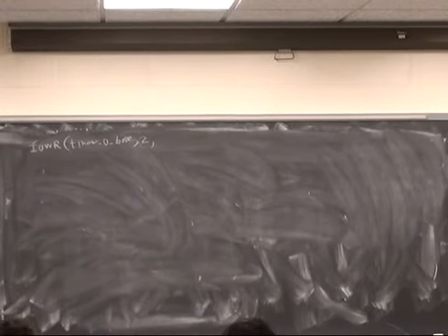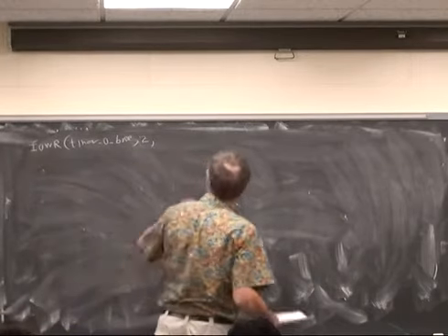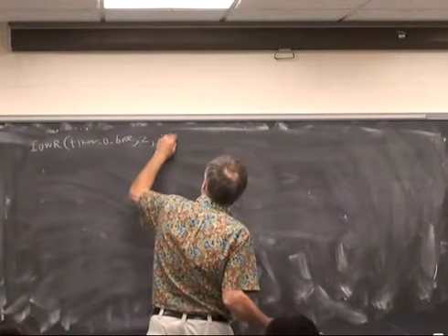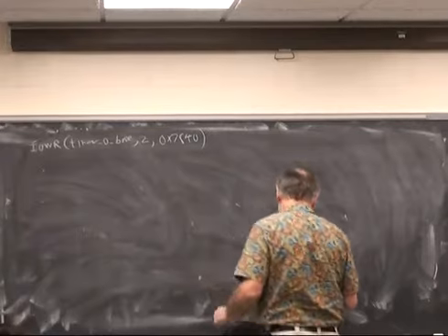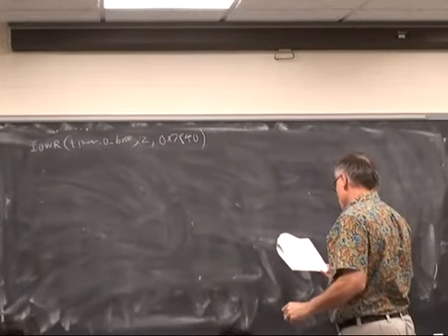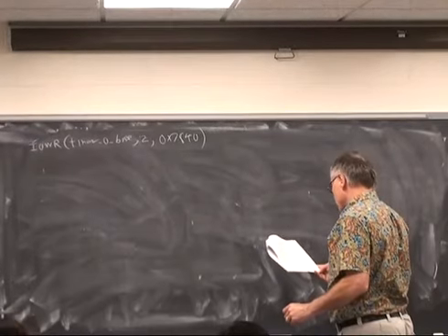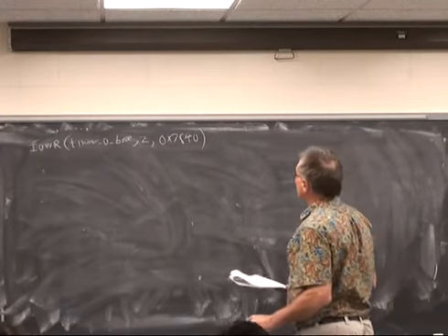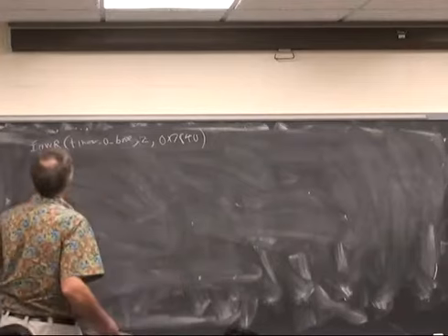So this is the low 16 bits, which we're going to set to 0x7840, and this comes from dividing. I wanted a half-second period here, and 25E6, 25 times 10 to the 6 counts, turned out to be hexadecimal 17D7840. So that's the low 16 bits.